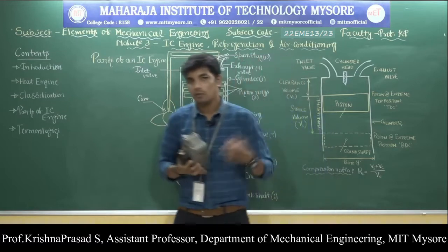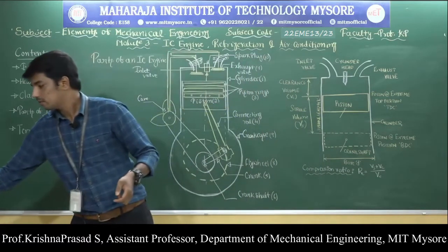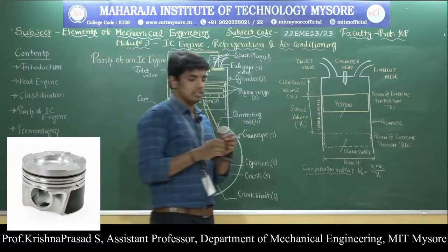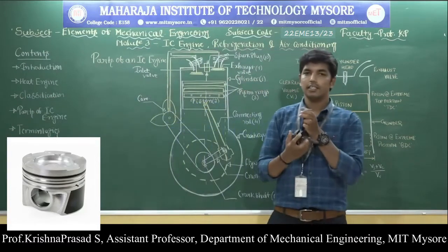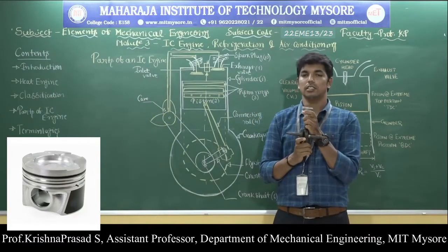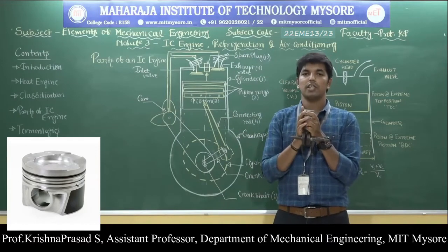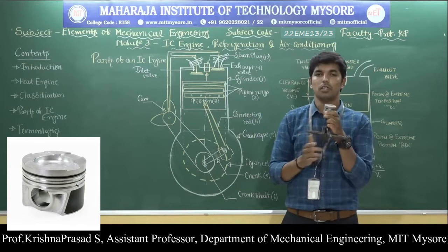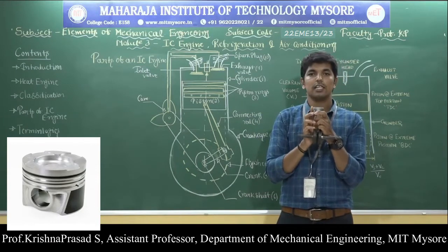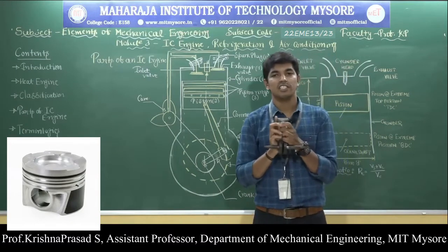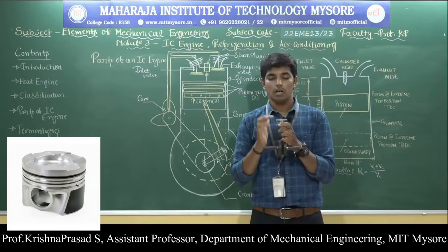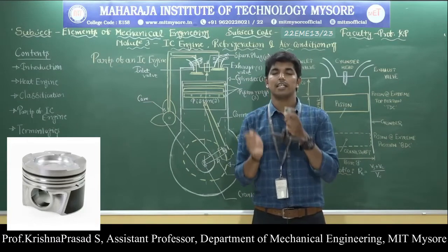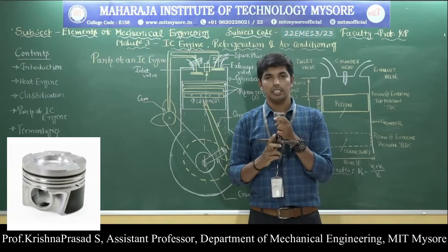Next, the second part: what is meant by the piston? The piston reciprocates inside the engine cylinder, and the construction of the piston is also very important. The piston is a cylindrical shaped component which perfectly fits inside the engine cylinder. That means the outer diameter of the piston must be exactly equal to the inner diameter of the engine cylinder.